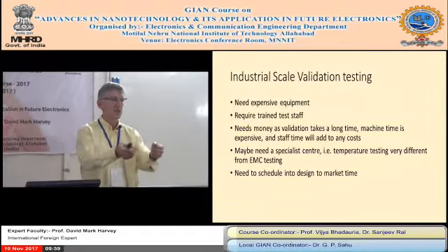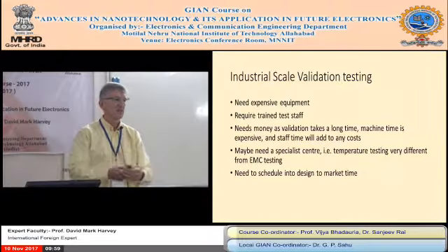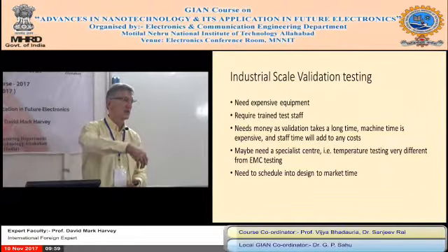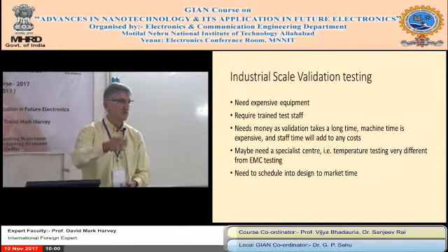You can put the circuit board in different directions. But it's not just an oven. Round the back, you have a connection panel, so you can test the circuit hot and cold while it's actually working. You'll drive the circuit in its normal operation with input signals, and you have a load bank. Say it's a car, it might be driving petrol injectors, so it'll have a bank that looks like a petrol injector.